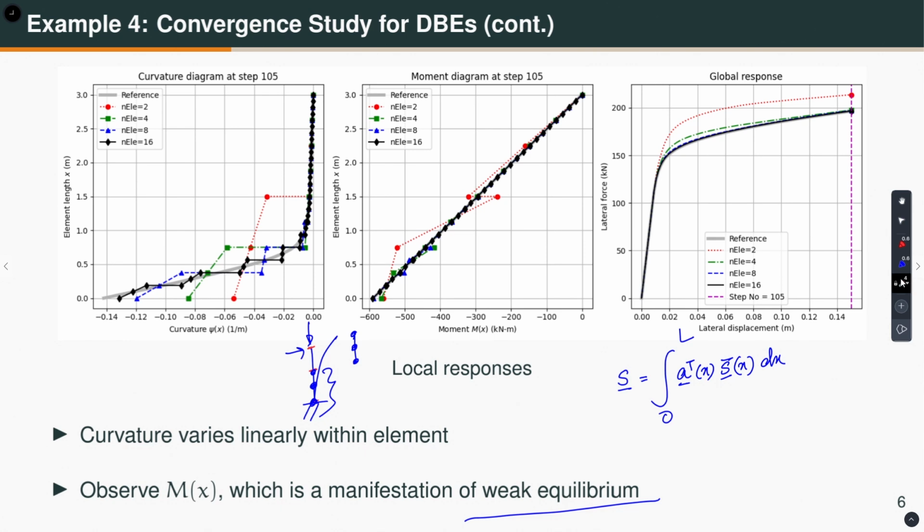Okay. So, because of this, just to remind you, what is S bar? S bar X is Nx and Mx, the forces at the section level, and S is equal to N, Mi and Mj, the axial force at the end of the element, the moment at end i and moment at end j in the simply supported basic or deformation coordinate system.